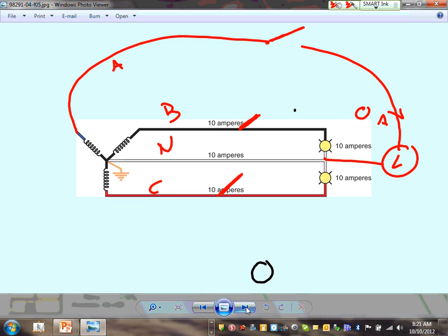So in this case, I don't have to have a separate disconnect. If I have multiple levels of lights, I can turn this set off and go work on it. That qualifies as the disconnect. Or what the industry standard is, guys, a little plug that you can plug and unplug to disconnect the ballast, for any ballasted equipment. Yeah, that's a standard.